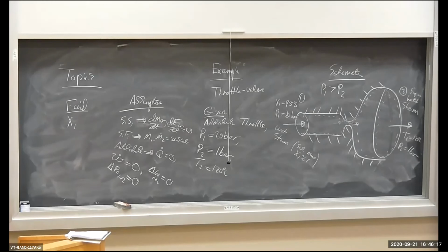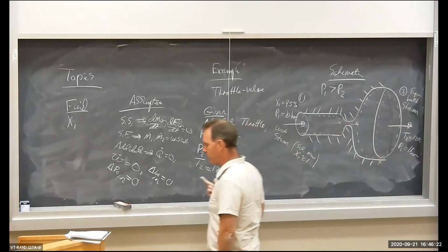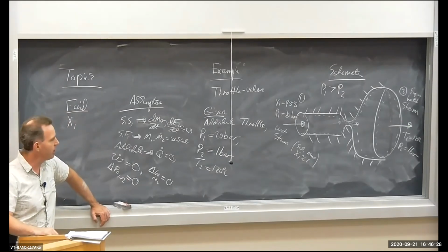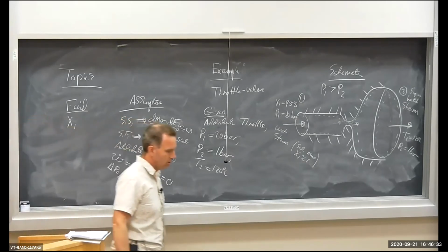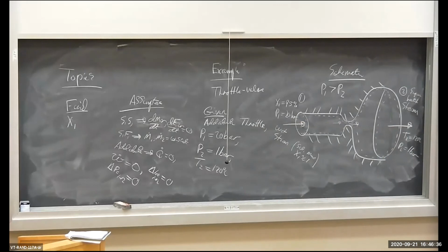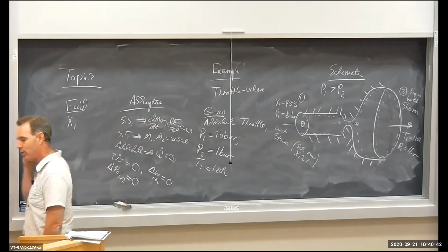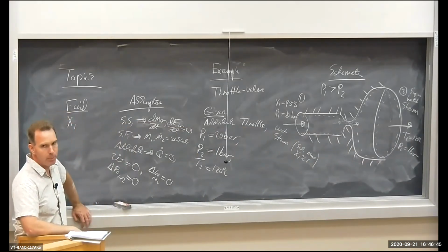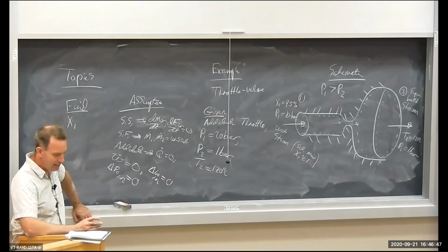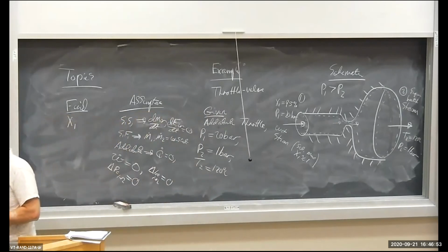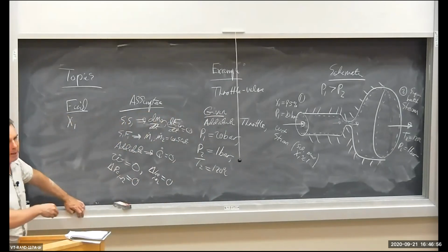So we learned how to apply the energy balance and mass balance to our first simple open flow device. A throttling valve, there's nothing going on in this valve. No heat transfer, no work. We're neglecting changes in kinetic and potential energy. Therefore, the energy balance tells us it's an isenthalpic, constant enthalpy process. H2 is equal to H1. Inlet enthalpy is equal to outlet enthalpy. And then we established that we started with a saturated mix, and we expanded to a superheated vapor.